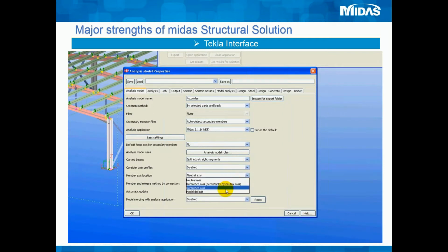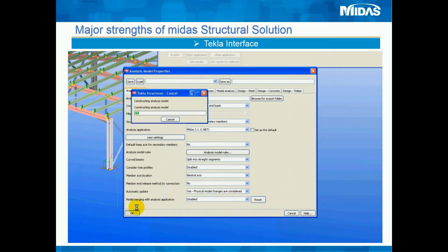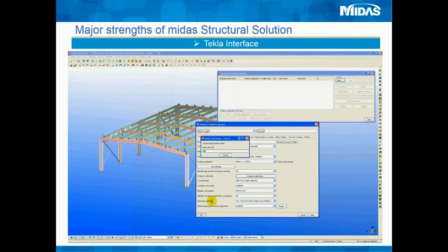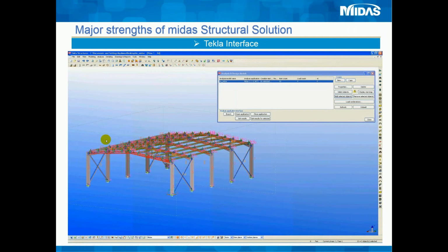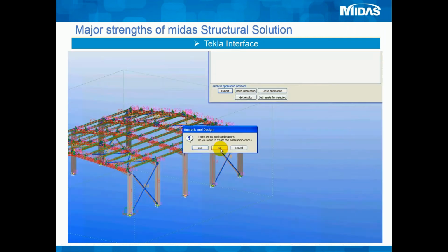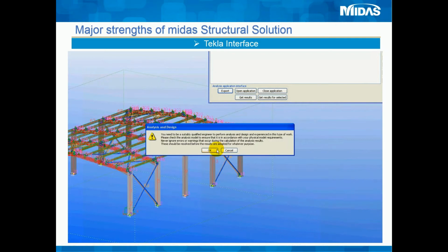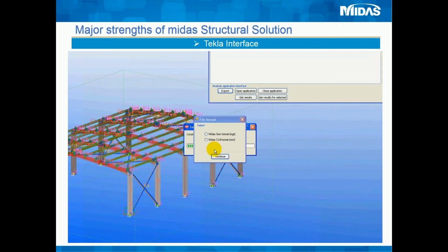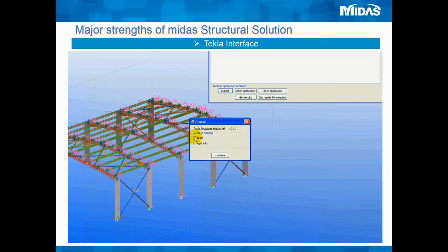This is basically the procedure for taking the Tekla model into the MIDAS Gen program. So Tekla is converted into a MIDAS Gen text file.